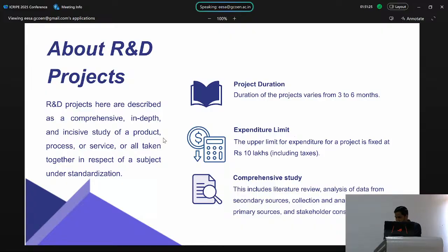I can give you one example of PVC pipe. PVC pipes are used for water supply in our homes and in our agriculture. There is one filler content, calcium carbonate, CaCO3, that is used in preparation of this PVC pipe. If a PVC pipe has a higher CaCO3 content, it will be brittle.